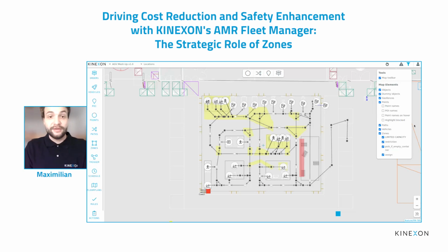And the third type of zones that we like to use is the zones that are evaluated by a real-time localization system. So it's like a combination of the fleet manager zones and the zones we send to the vehicle. But the difference is those kinds of zones refer to the actual location of the vehicle. With that information, we are able to trigger other logics. For example, we can also incorporate forklifts with that, and those forklifts can then be used to do collision avoidance.